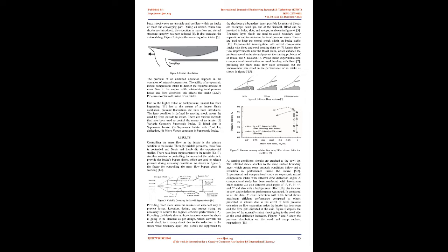During the operating condition of an intake, flow can be achieved in 2 ways. 1. At designed Mach number conditions, the intake will capture a significant amount of mass flow, which creates equivalent shock waves, which results in proper compression happening due to reduction in total pressure and reduction in Mach number. This is called the start of an intake.